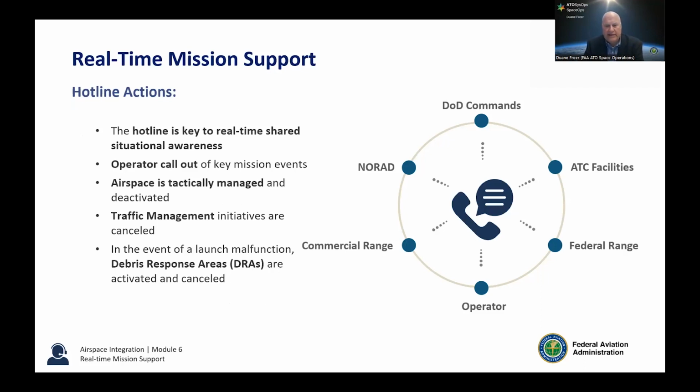These are the different entities. You'll see we have our own Department of Defense, our air traffic control facilities, federal ranges, the operator. If it's a commercial range, we'll have them on. And again, all those entities have the same situational awareness in real time. The operator will often, in the letter agreement, make certain call outs to us. Let's say T-minus 10 minutes. We'll have them call out launch, stage separation, and then mission completion.